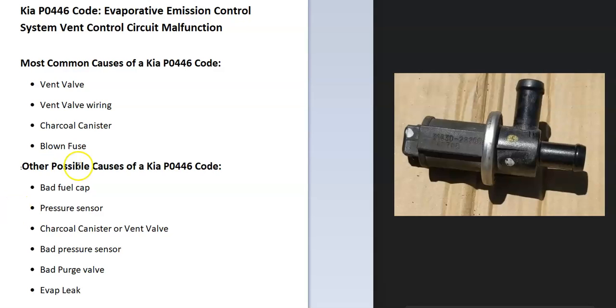And there are some other things that might cause a P0446, but usually if it's these problems right here, you'll get another code. So if you are getting other codes, you might want to look those up and see if there's not some other kind of issue that's just causing a problem down the line. But the most common causes for P0446 is going to be around the vent valve.